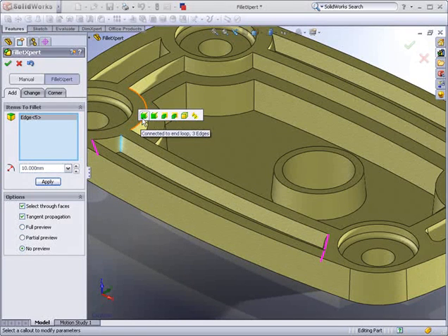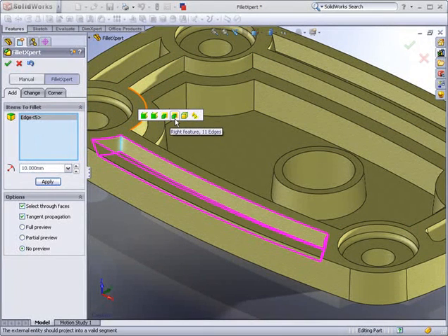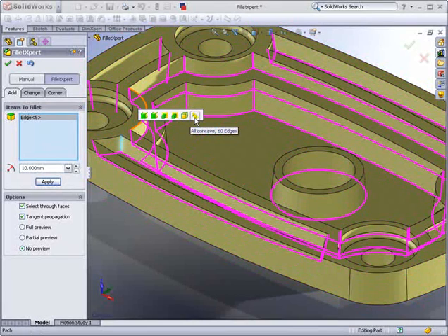In this case, these options are connected to end loop, the edges connected to the bottom face of the feature, connected to end internal loops, the edges connected to the top face of this feature, internal to feature, all the edges connected internally to this feature, right feature, all the edges connected to this feature, all the edges in the entire part, and all concave, all the edges that result in concave fillets. Notice that in each option the number of edges selected is shown.